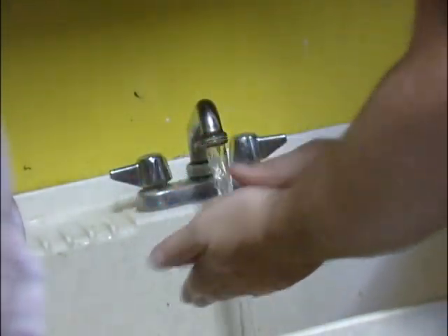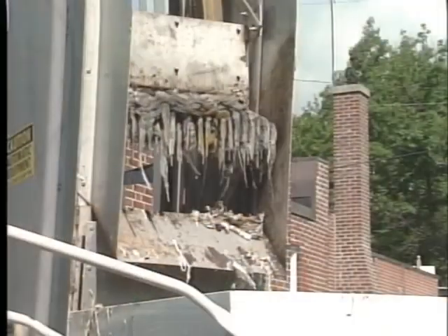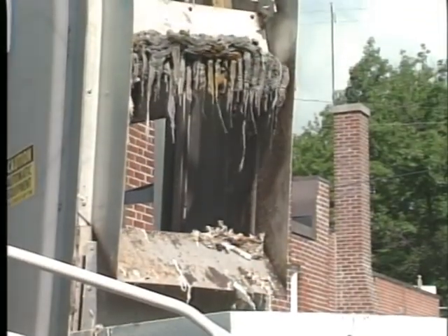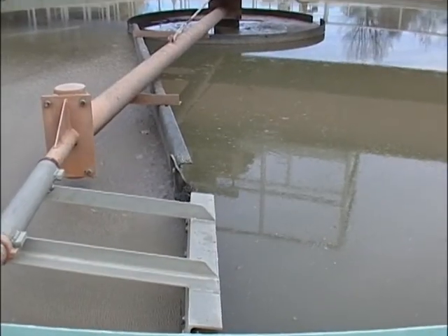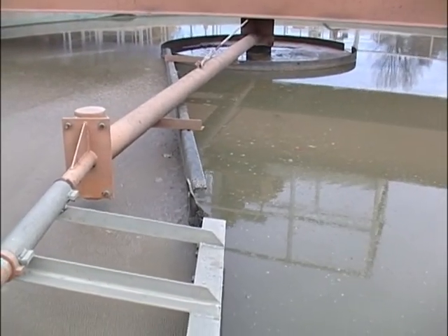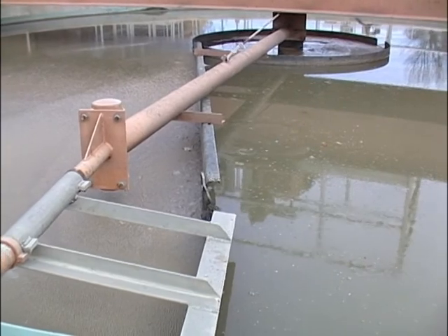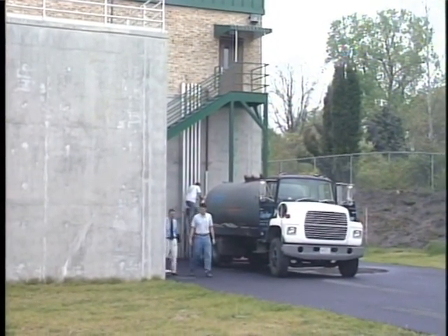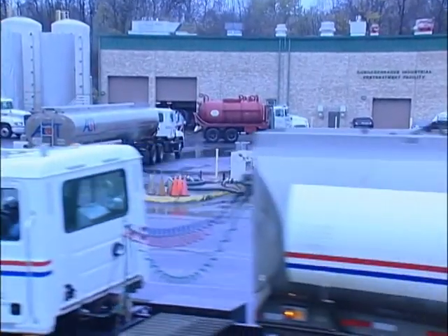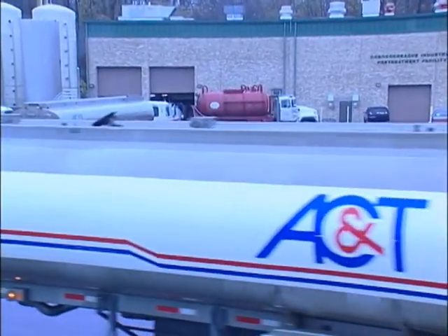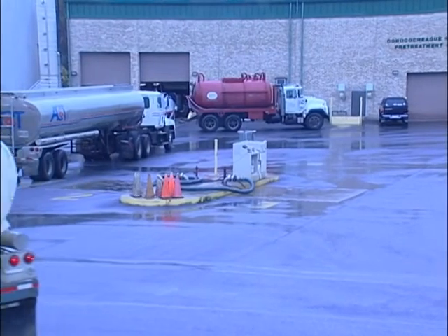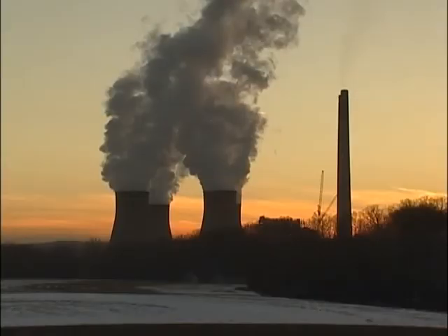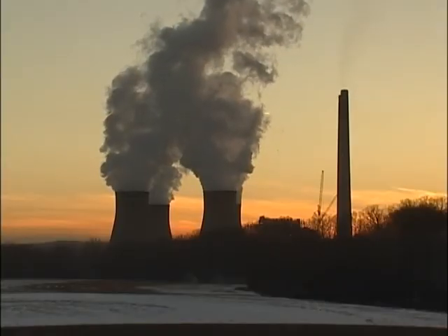From the time the wastewater is generated, through the collection system and through all of the treatment processes in a treatment plant, the process of nitrification can be impacted by anything that happens upstream. For example, certain substances that could be accidentally or intentionally dumped into your system could cause the loss of nitrification. The development and enforcement of sewer use ordinances can reduce the likelihood of unwanted substances entering your system.